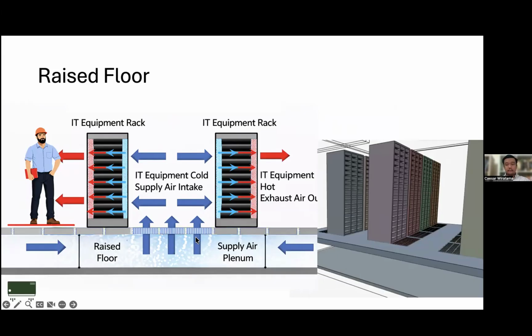Most data center buildings will have this raised floor for this purpose, but not all. Sometimes we also have some local systems above the floor that we will discuss later. But this is again the most commonly used strategy for data center HVAC air distribution.